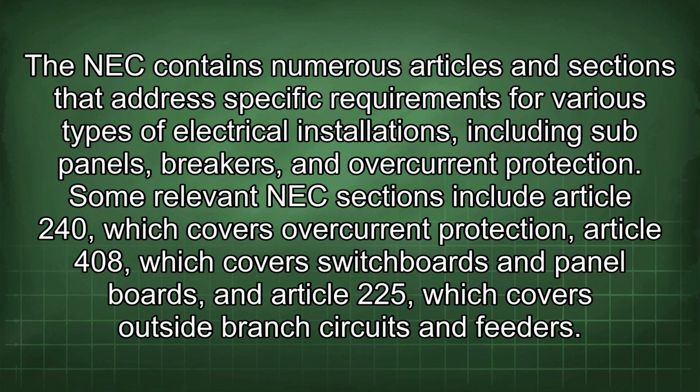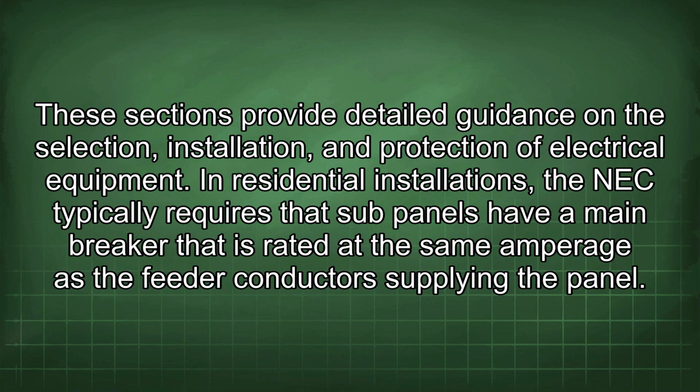Some relevant NEC sections include Article 240, which covers overcurrent protection, Article 408, which covers switchboards and panelboards, and Article 225, which covers outside branch circuits and feeders. These sections provide detailed guidance on the selection, installation, and protection of electrical equipment.